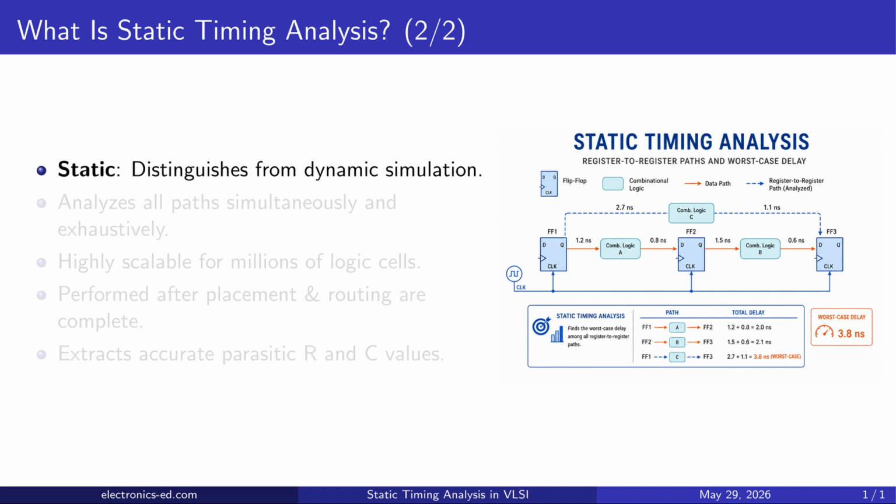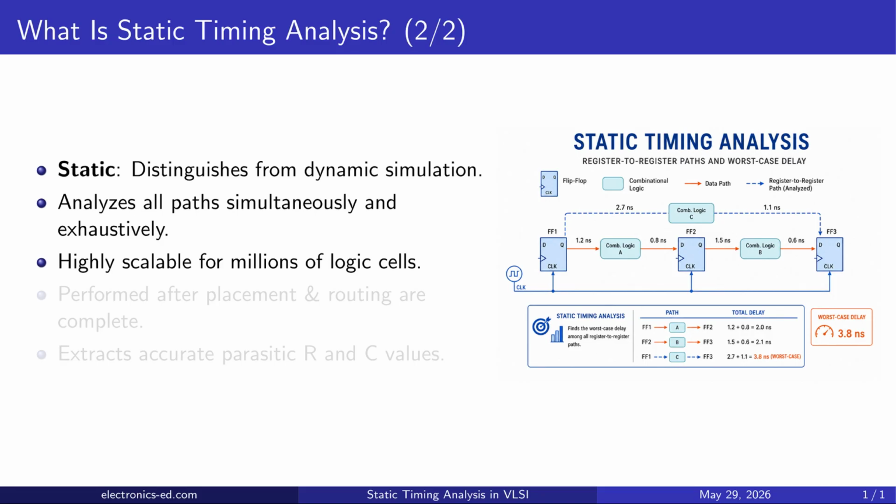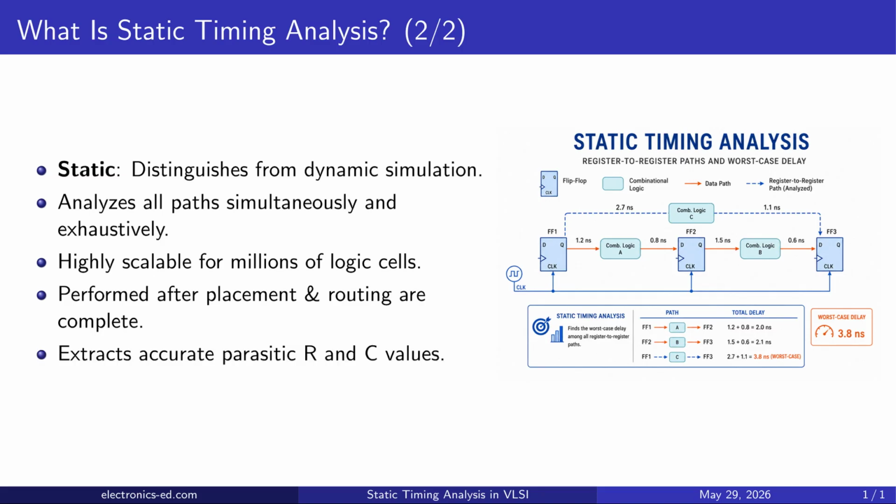The term static distinguishes this approach from dynamic simulation, which applies specific input patterns. STA analyzes all timing paths simultaneously and exhaustively, leaving no path unchecked. This method is highly scalable, so it works even for designs with millions of logic cells. STA is typically performed after placement and routing are already complete. It extracts accurate parasitic resistance and capacitance values from the routed layout.